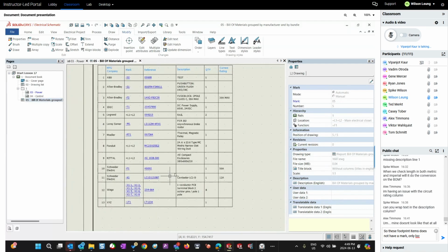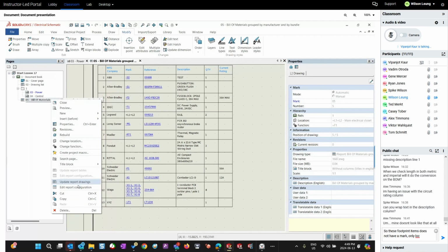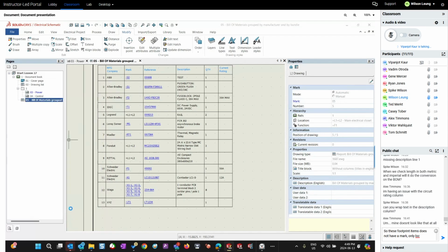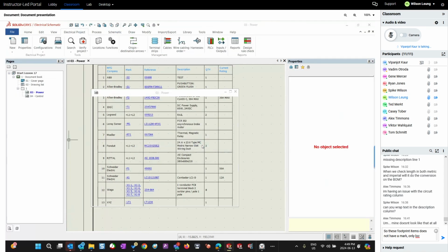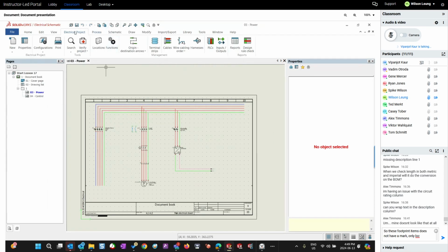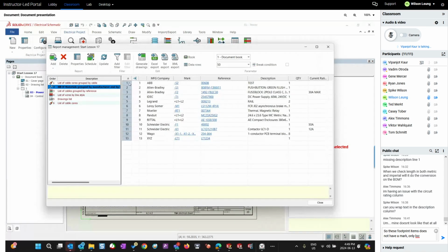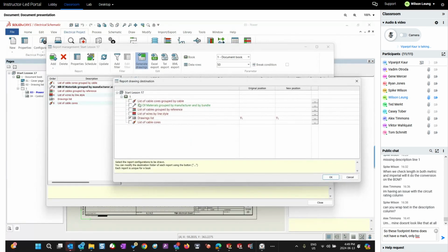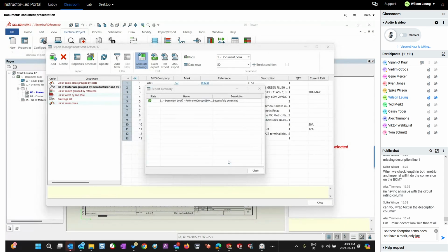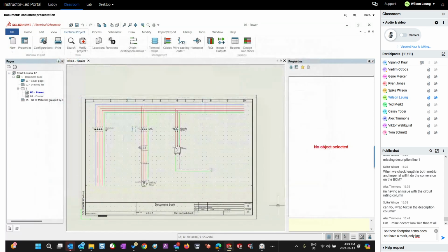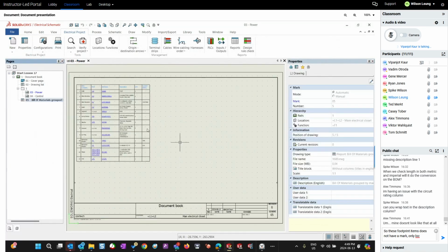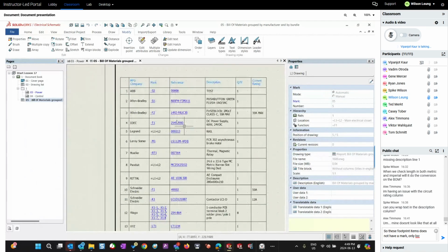The only way I can fix the mess, if I want to update the report in future, is to delete the report and create it again. So I have to go back to project reports. Now I have to click on the BOM report to generate a report again. So exploding messes it up. It breaks the hyperlinks. It breaks the motive of updating reports. Update will never work for you.